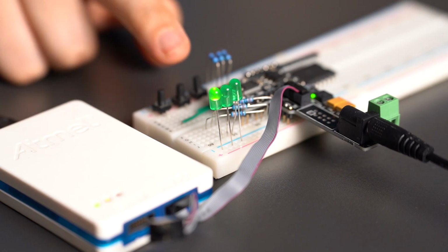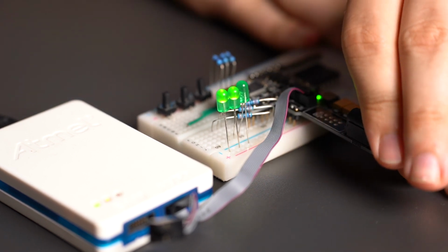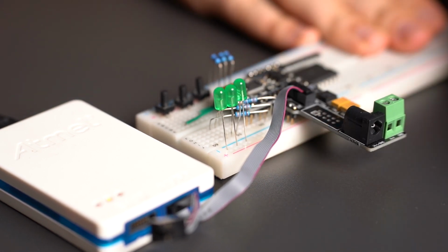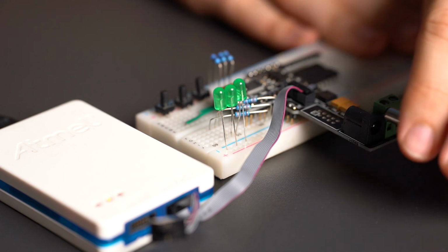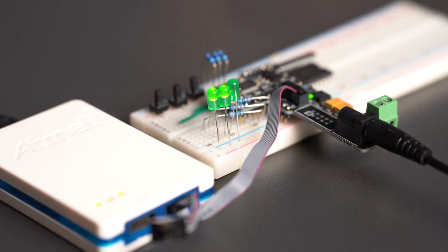Now, let's see if our EEPROM memory really works. Set a code combination, then disconnect the power to the circuit. You can see that the system is now powered off and the LEDs are off. As soon as I plug the power supply back, the same two LEDs should light up as before the power was off. You can see that this has happened, so we have managed to save our settings to the EEPROM.